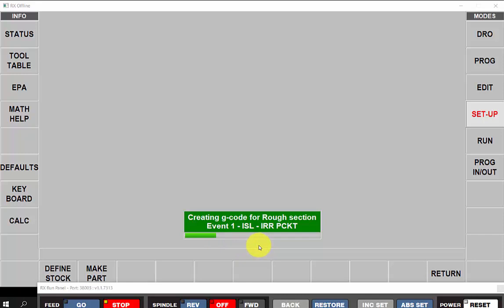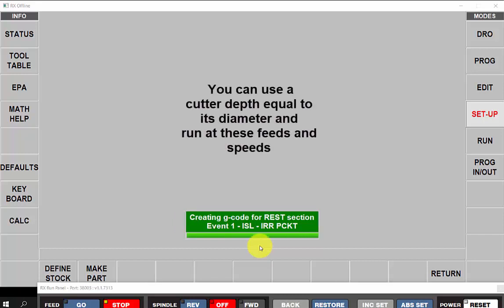The reason being the strategy that I picked for this is adaptive machining, which is circular cutting, using 30% of the 35% of the end mill per pass. I'm cutting it one way, which means I'm always in climb cut mode. And this is what allows me to program the feeds and speeds that you saw. We were doing a helix into the part at 40 inches a minute. We were roughing at 80 inches a minute and finishing at 60.